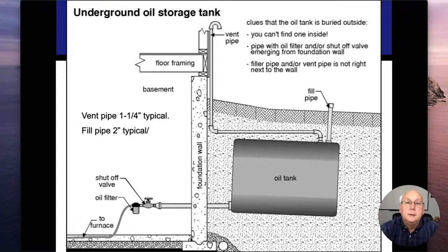In our area, if we have an unused, buried storage tank, it has to be removed. It's not cheap, and especially if it's leaked in the past, then it gets pretty expensive. So the guys that remove these tanks, they're going to dig around the area, remove all the soil, especially anything that could have been polluted with the oil. They're going to make sure all that soil is removed as well. Then they have to come back and put additional material back in there.